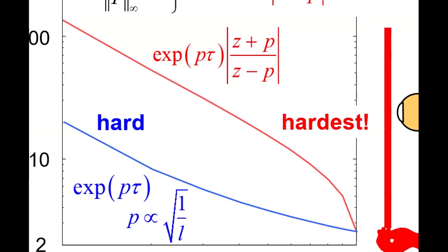Tau is the time delay in your visual core, through vision. And P is the pole location of the instability. So this is an unstable pole, so it goes like e to the pt. It falls over like e to the pt, and then I just plug in the delay and I get e to the p tau. The thing about this is that the exponential increases exponentially with t.